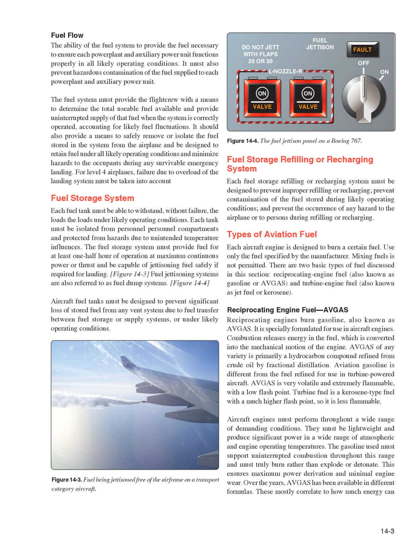It should also provide a means to safely remove or isolate the fuel stored in the system from the airplane and be designed to retain fuel under all likely operating conditions and minimize hazards to the occupants during any survivable emergency landing. For Level 4 airplanes, failure due to overload of the landing system must be taken into account.